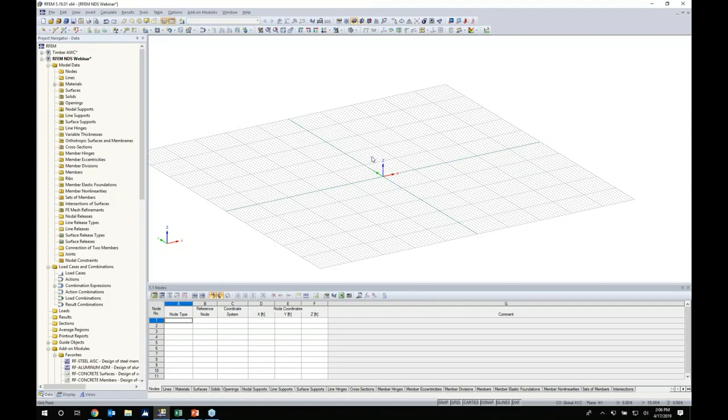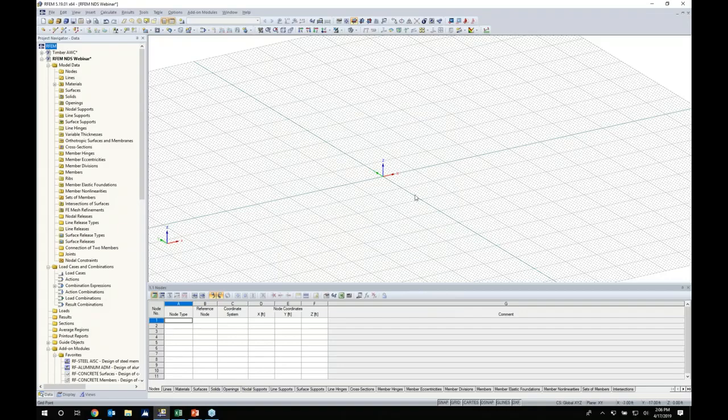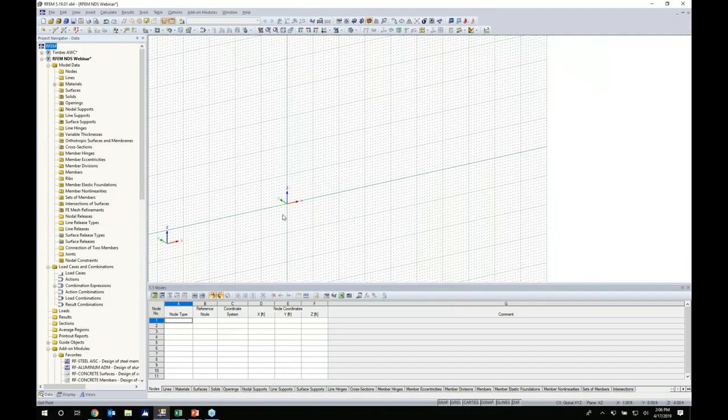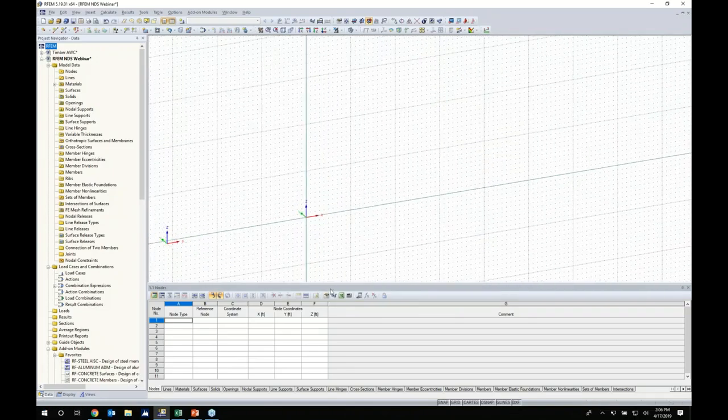So to begin with, I want to go ahead and expand my grid settings here. So I can right click under my grid to edit it. And instead of the default options of 50 feet on any side of the grid origin, we're going to change this to 100. Our model is quite bigger than this today, so this will just be helpful with modeling. So now you can see just my project grid here. What I can do is to change the work plane here according to the ZX plane. And we'll begin by drawing our first member.